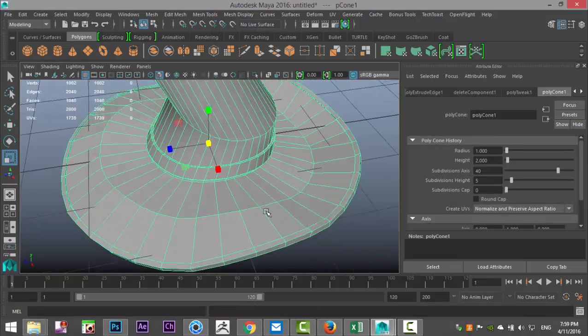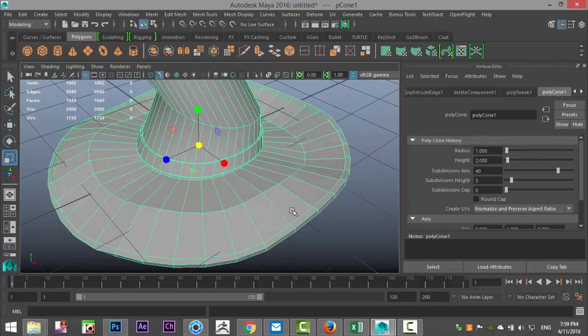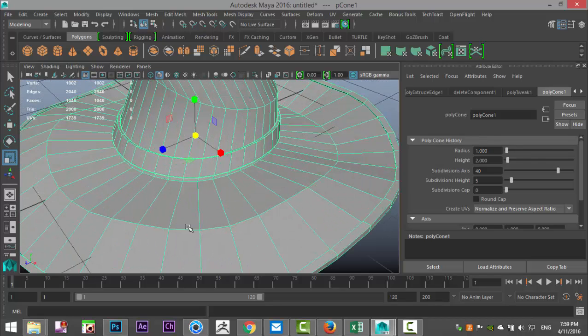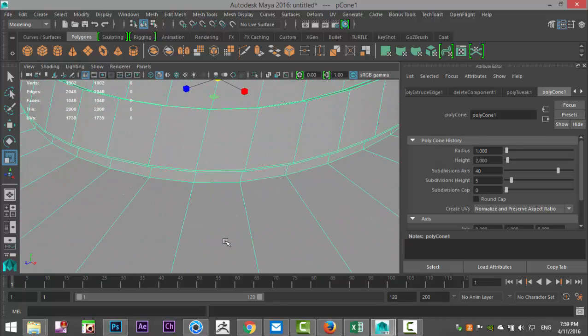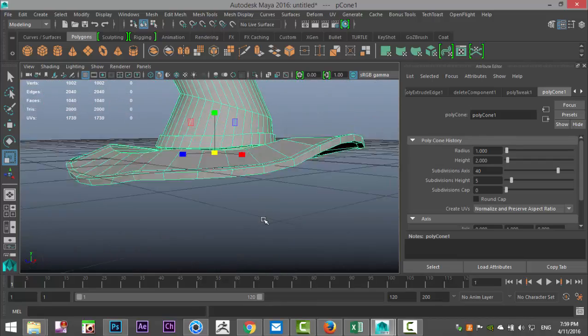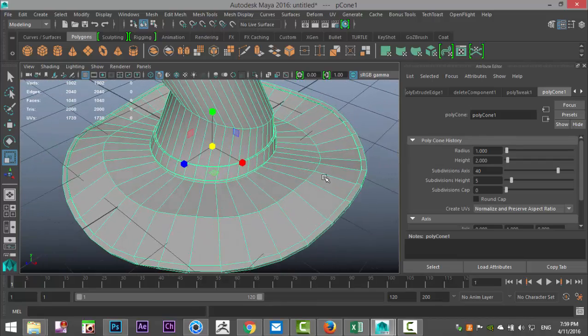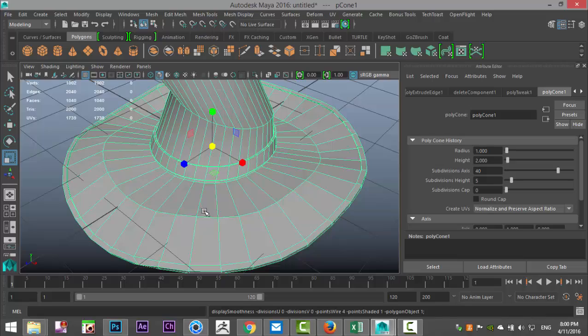And it looks like the problem is caused by the extrusion. Now what happens there is when we hit extrude, all the faces are pulled outwards. So faces that are very close together will run into an issue, probably in these corners here. So the only thing we do is we hit Control Z to go back. We've got our entire model selected. And let's go to 3 to preview smooth. And you can see that it's smoothing too much right there.